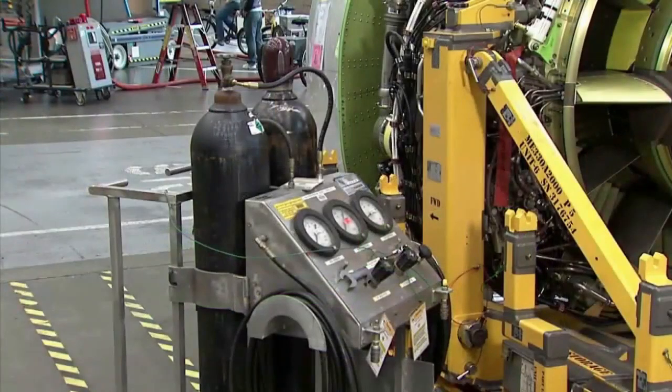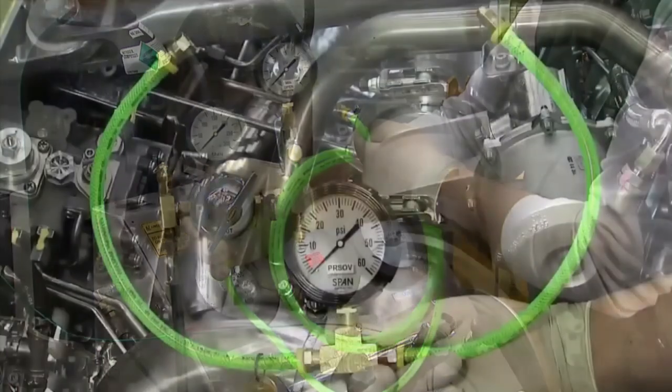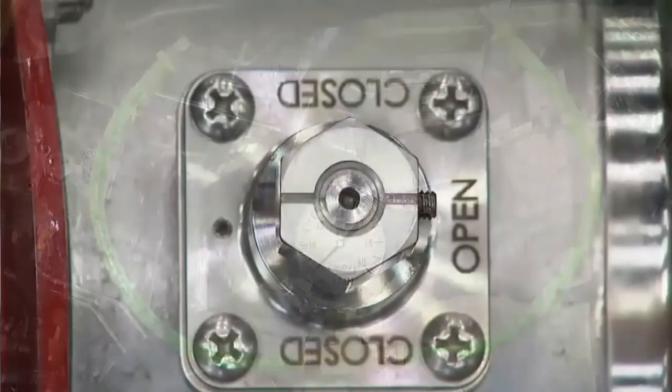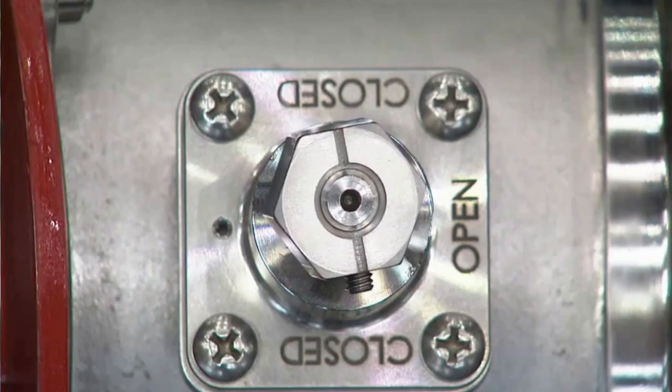You will also need a source of supply pressure. In our example, we will be using nitrogen. See your AMM for more information. You use a nitrogen and test supply assembly consisting of hoses, pressure gauges and regulators to simulate engine supply pressure in the system, and control pressure gauges, hoses and fittings to monitor the control pressure. Note that in some cases you may also need to monitor the movement of the valves.